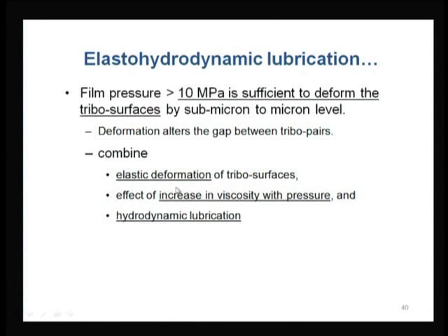But this says clearly that the increase in viscosity, from the previous table that was shown to us, is that if pressure is not very high, then there is a possibility of increase in viscosity, but not to a greater level. When we talk about something like 100 bar or 10 megapascal, we found the increase in viscosity is only 10%, it is not a very high percentage. And again, if there is a relative velocity effect, velocity is higher, and the rolling contact is not happening for a longer duration, then the viscosity effect will not be dominating either. We are hypothetically thinking about 10%, it may not turn out to be 10%, maybe 2%, 3%, depending on the relative velocity. So, that may not happen substantially.